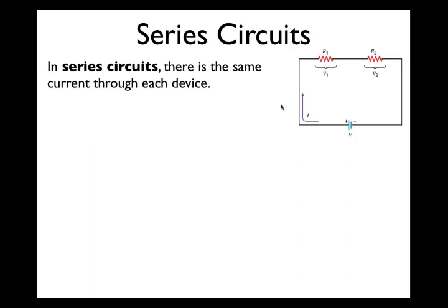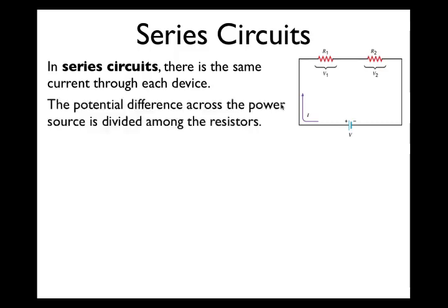This is confusing to some people because, again, you expect something to have diminished after the charge has flowed through each resistor. And in fact, something has diminished, but it's not current. Current, you'll recall, is charge per time. So all we're saying by saying the current is the same everywhere in this circuit is that there are the same number of charges passing each observation point per time. In other words, we're not creating charge, we're not destroying charge, we're not building charge up within the resistors, we're just pushing charge around this loop.